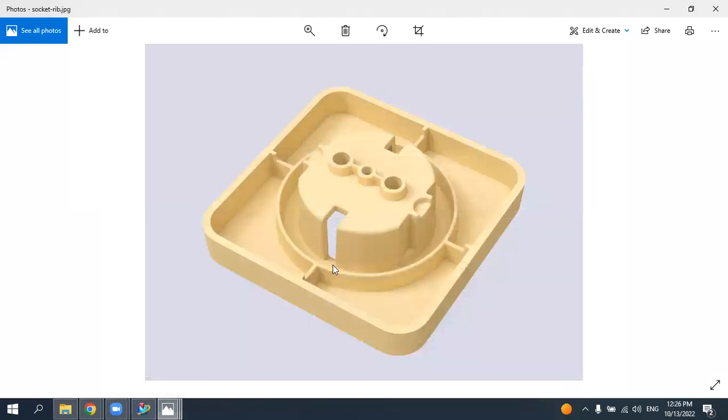For example, we can firstly create this element here with these elements. Firstly, let's do this. This is called a rib in the plastic element. So it is like the supporting elements in the plastic elements, because as you know the plastic elements are too weak. It could break down in the moment. So these are the systems. It's called ribs. So it is used to increase the strength of the plastic elements as supporting elements.